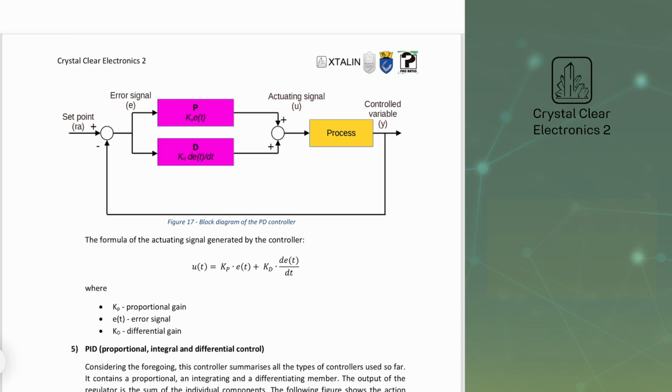Although the residual error is eliminated, the integrator term will cause the system to settle more slowly to the final value, its overshoot will increase, and its stability will deteriorate. If we want to improve the response time of the controller, we need to implement a differential component in our controller. The PID controller is appropriate for this application, so we will proceed with it.